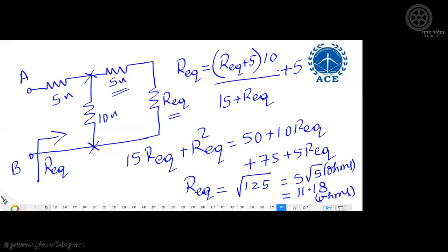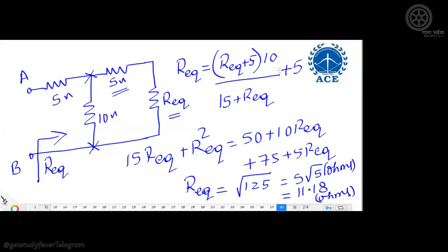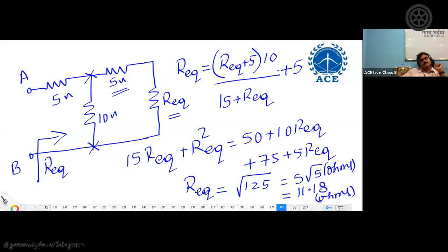Come again? Sorry. That current source, whatever you are representing in parallel with the inductor, when I have again opened the switch for removing my source, in the last part of the question, we have removed the source. Yes, sir. At that time only we are showing this. Then again you have to show this. Otherwise, initially when you are drawing the circuit after 0 plus, there is no initial value of the current on the inductor, so you need not keep anything in parallel.